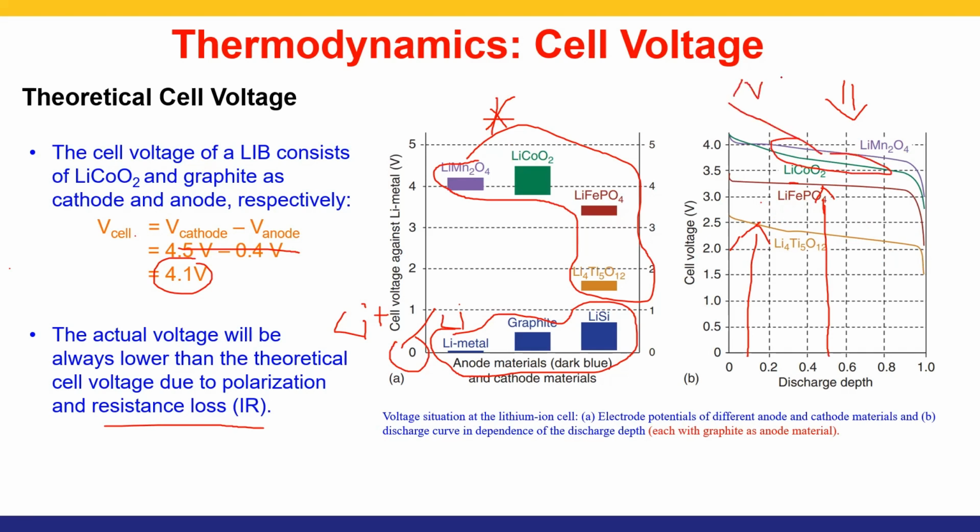As mentioned previously, a battery cannot be fully discharged because it will destabilize the electrode structures, and therefore there is always a cut-off voltage to prevent the battery from further discharge and to increase the lifetime of a battery.